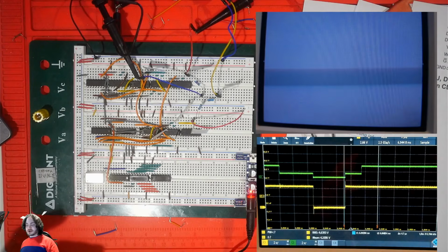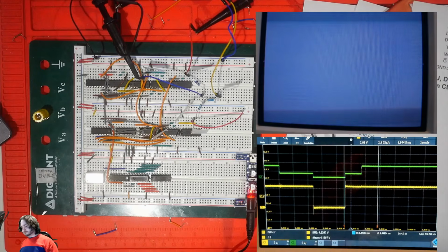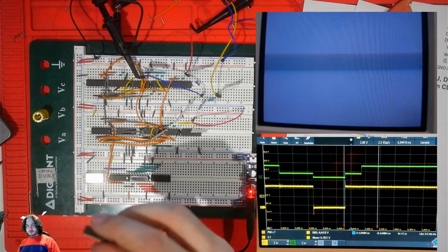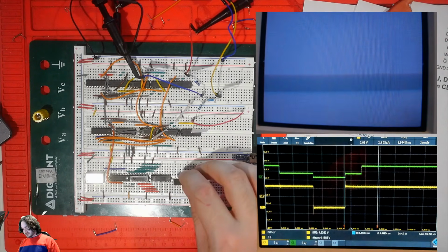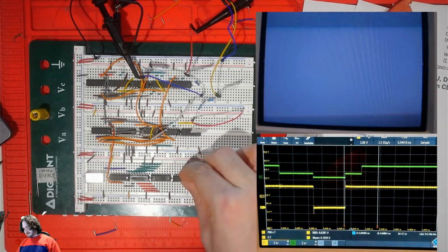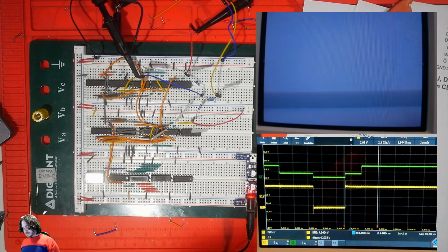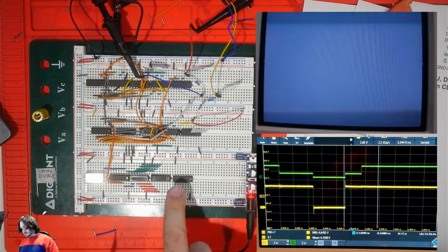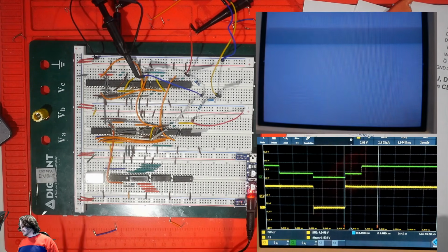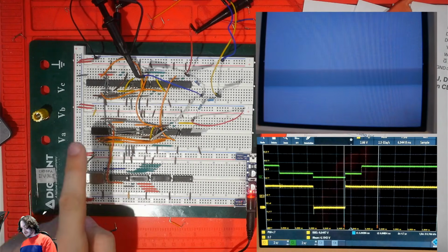That'll also throw the sync off. So that's three things we need to NAND together. So we need one more NAND gate, and we're going to stick this over here. And build another triple NAND. That's going to be based on not V-blank, H-blank, and 64H.